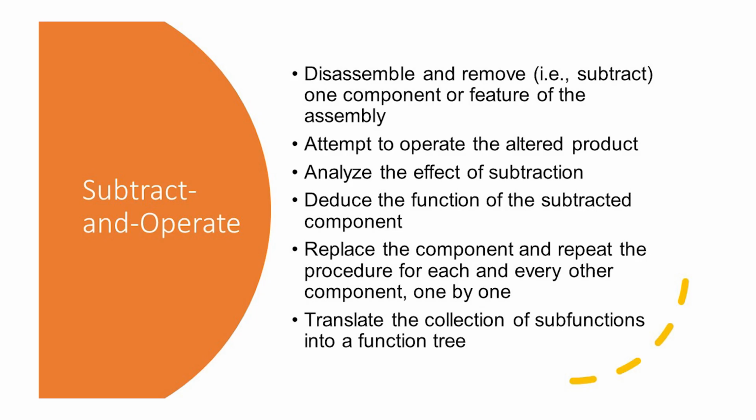So, translate the collection of sub functions. For each part that you disassemble and remove, you will get a sub function and then you can collect these sub functions and create a function tree. It is not just about okay, there is a product, we just break it down, we know all the parts and we can make our own product. No, you also want to know what is the function of each part in that product, and only when you deduce the function can you realize your own product and get it to work.